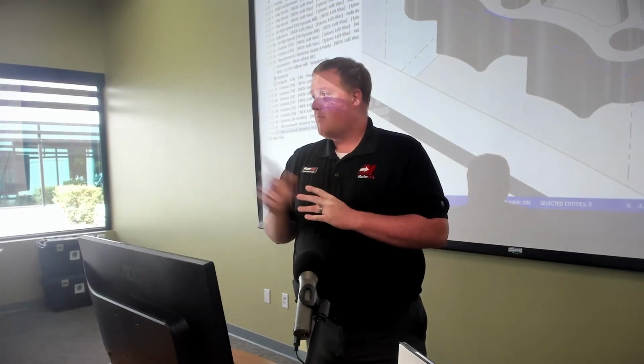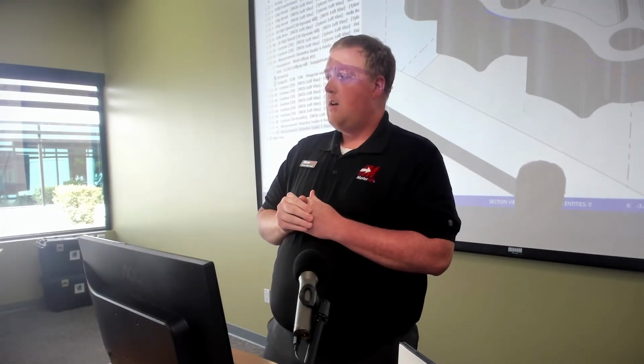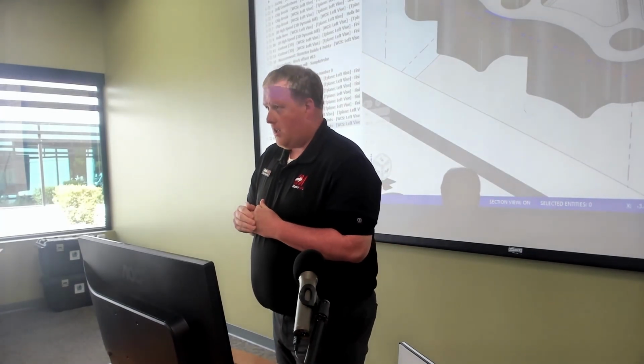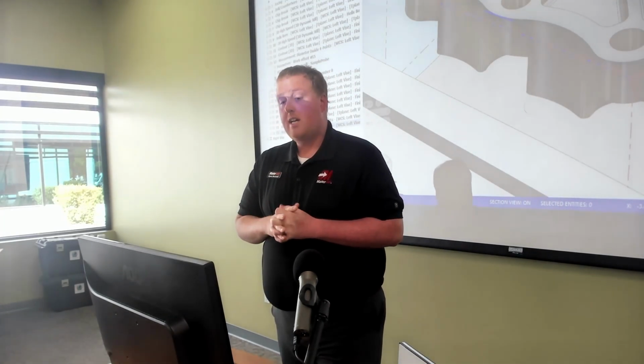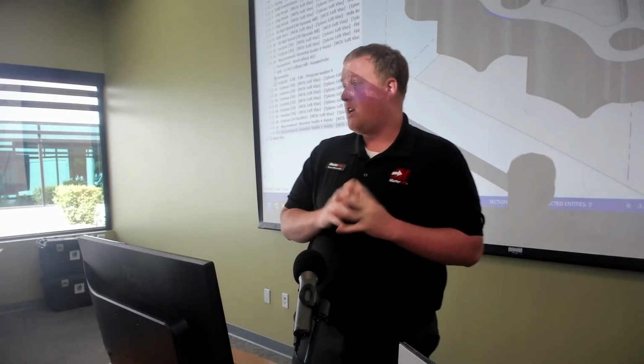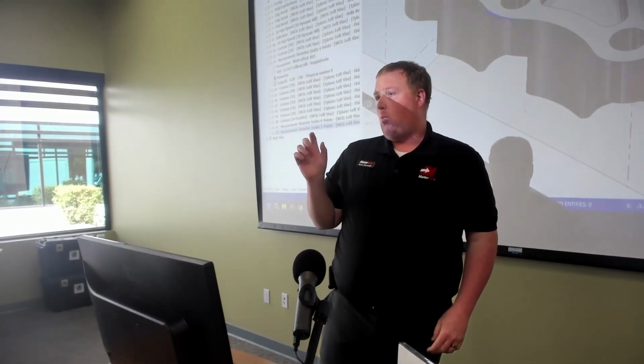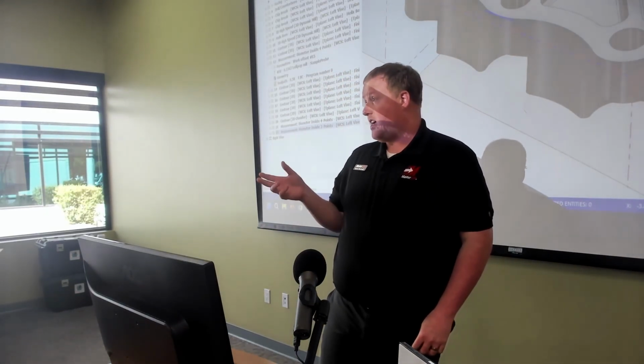So. Is the post-processor integrated into your existing Mastercam? Yeah, so for those that aren't running probing yet, there are some post modifications that do need to be implemented into the post processor. They're fairly simple changes, but they just need to be done in there. And part of that is going to be defining what probe and what control type it's going to be on.